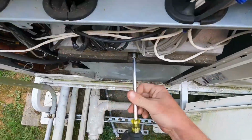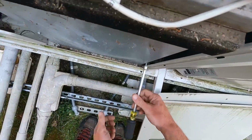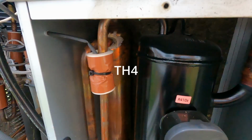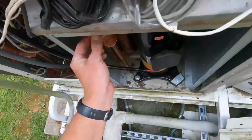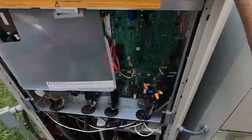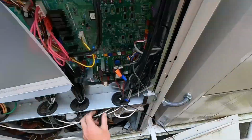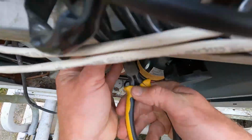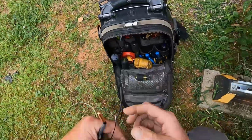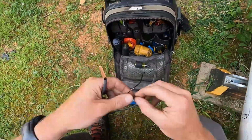TH4 reads discharge line temperature and is located between the compressor and the oil separator on the discharge line. This is a proprietary negative temperature coefficient thermistor with non-standard resistance values between 10 and 700 kiloohms, which lands on the printed circuit board on pins 3 and 4 of a green Molex connection, which is labeled CN211.